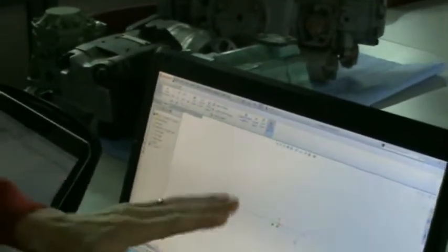So I can press escape for now. It's not necessarily blue. These two points are blue or black. It doesn't matter because a center line seems like it is endlessly long. This line we need to revolve when we do the construction. When we draw our model this way here, it's no problem. The center line is always in mind endlessly. So we take a line, we sketch a line, and make a cylinder this way.